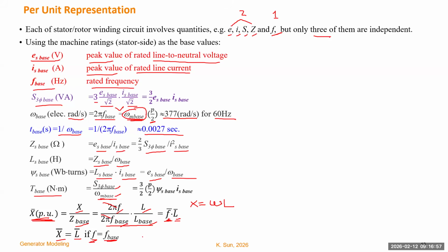That is why some software for power system simulation likes to use L everywhere, which can actually mean reactance, while other software uses X. In the later equations, we will use X for the equations about voltage, where you will see X multiplied by current give you some voltage drop on a certain branch of the inductance. If it's in the flux equation, we'll use XL.